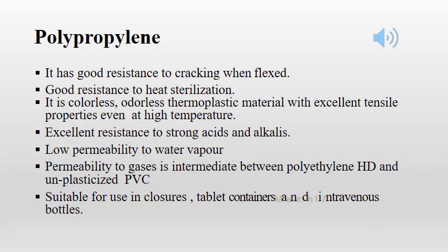Polypropylene type of plastic has a greater resistance against cracking and is comparatively more non-reactive against most of the organic solvents. It also tolerates sterilization temperature and has good impermeability against gases. But on exposure to lower temperature, it may become brittle. Therefore, polypropylene cannot be stored in a freezer. Because of their high mechanical strength, they are used to make closures with hinges. Its containers are also used for shock-proof packaging for tablets and capsules.